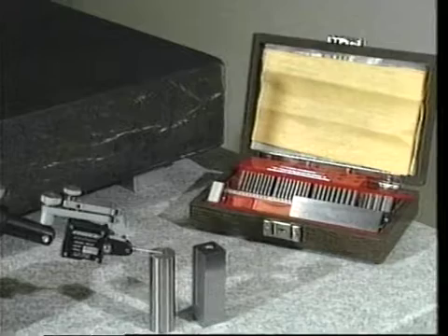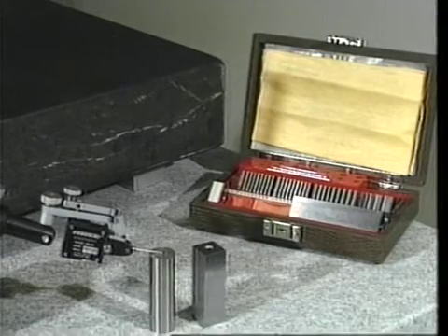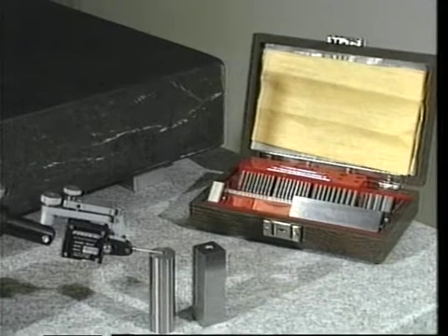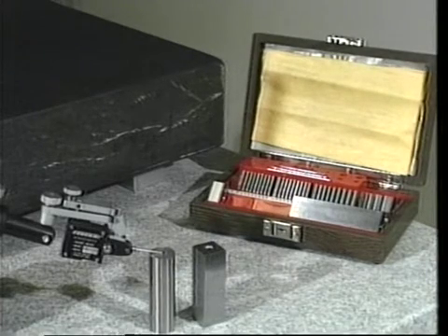Whether measuring the axis of motion of a translating carriage or the area of a surface plate, the technique is fundamentally the same. Uniformly spaced points are located along a measurement path. Angles between adjacent points are measured. These angles are converted to height differences, and a profile of the measurement path is plotted from the relative heights of the sampled points. In our measurement, we wish to record the general shape of the surface or the very low frequency waviness present in the surface.